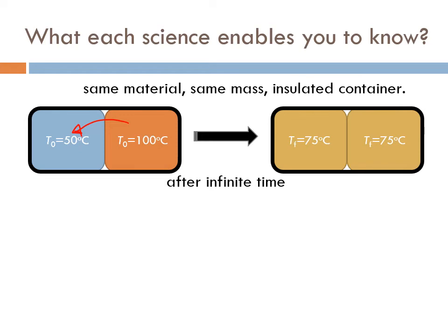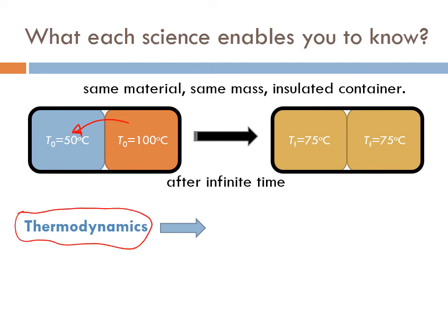What's the equilibrium temperature? Well, you need to calculate it, right? How do you calculate it? You will calculate it through the knowledge of thermodynamics, the first law of thermodynamics. Remember, delta E equals input minus output. The system is insulated, so the change in energy is 0. Delta E equals 0, with no change in kinetic or potential energy, so you end up with delta U equals 0, and this consists of delta U system 1 plus delta U system 2 equals 0, where 1 is block 1 and 2 is the second block, and you know how to calculate the delta U.